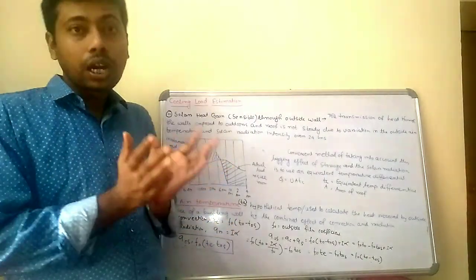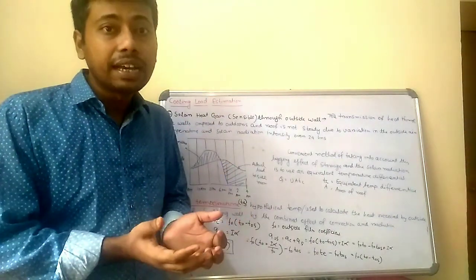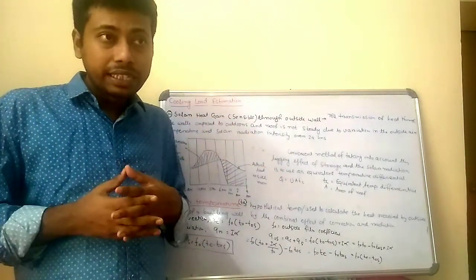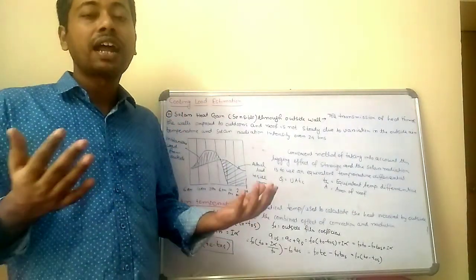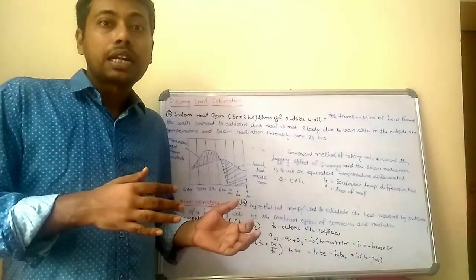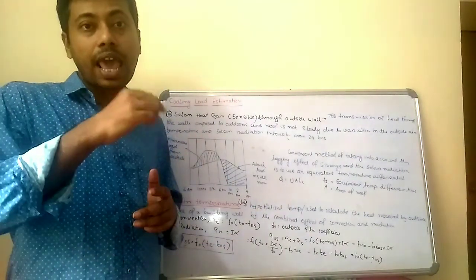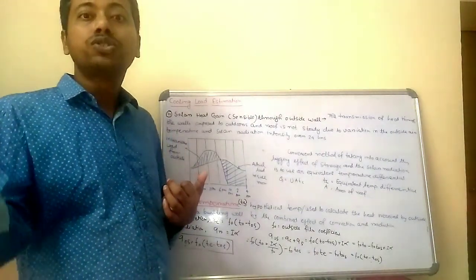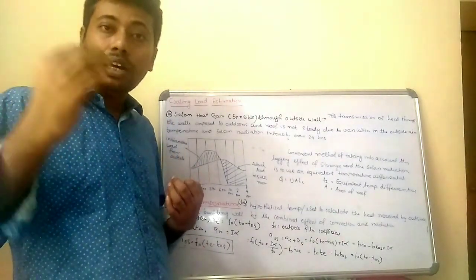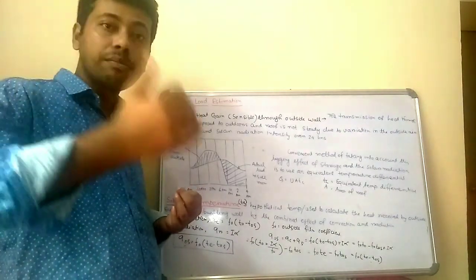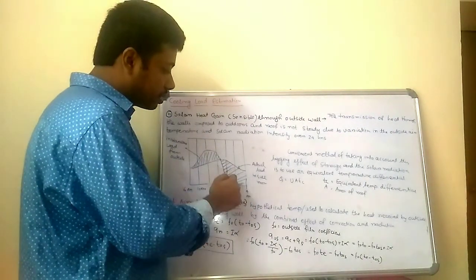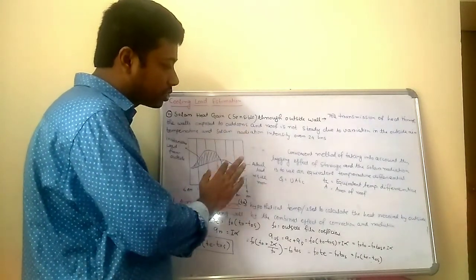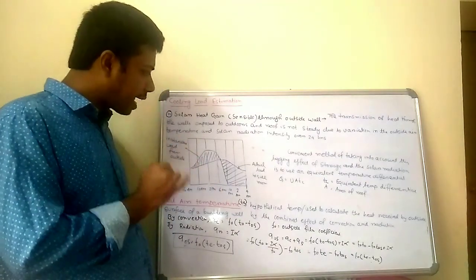So there are two curves from which you can get an idea of the temperature variation throughout the whole day. Due to the temperature difference and the solar intensity, there are two curves. The upper curve is the actual instantaneous load from outside, at the instant the solar intensity comes from the sun. The lower curve is the actual instantaneous load inside the room.